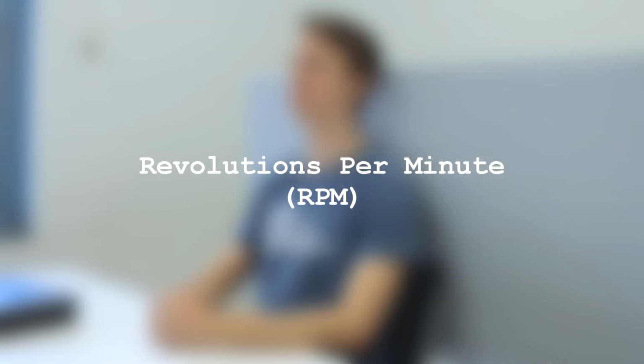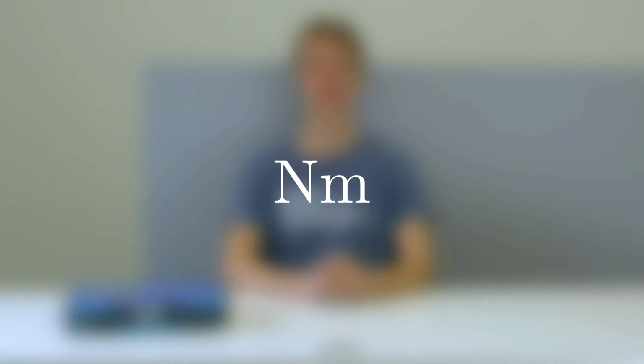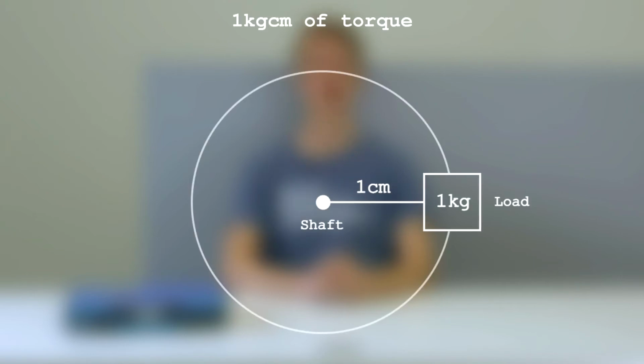Of these, the first you will have to think about is the speed and torque of the motor. The speed in datasheets is usually for when there is no load on the motor. The speed is expressed as revolutions per minute, RPM for short. The torque is expressed as Newton meters or more often as kilogram centimeters. The torque tells how much weight or force the motor can output at a specific distance from the shaft. If you want more torque and can sacrifice speed, we recommend looking into gearing and gearboxes.